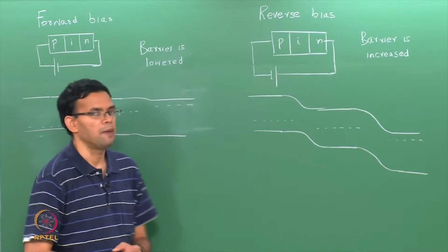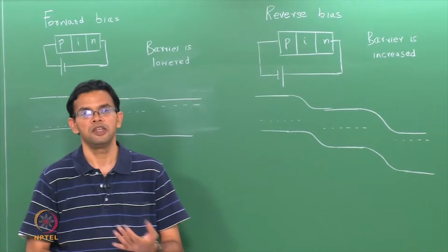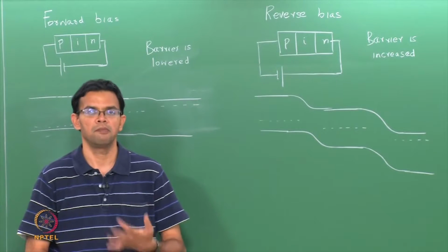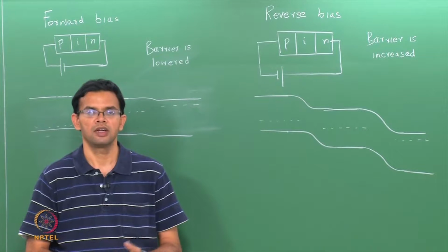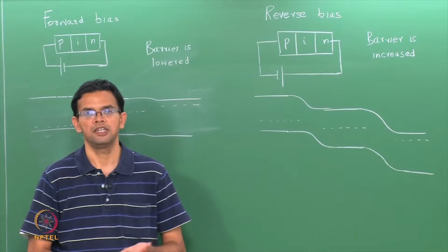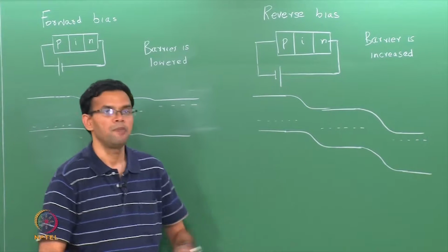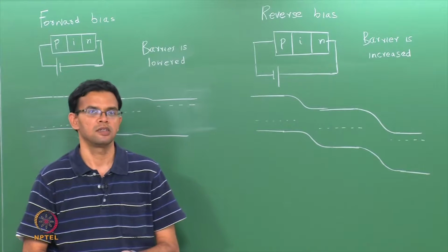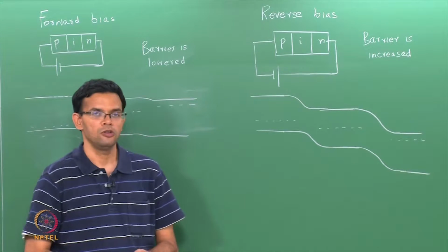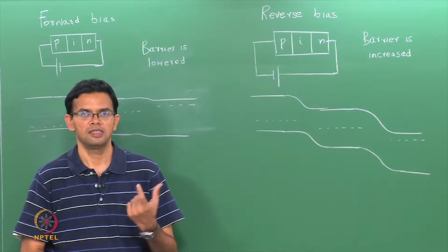For this to happen, we essentially want the current through the device to be very small, because if there is a background current, that will essentially act as noise to the current that is generated by light shining on the material. This happens when the PIN junction is connected in reverse bias, so that electrons and holes that are typically created in the intrinsic region get separated.